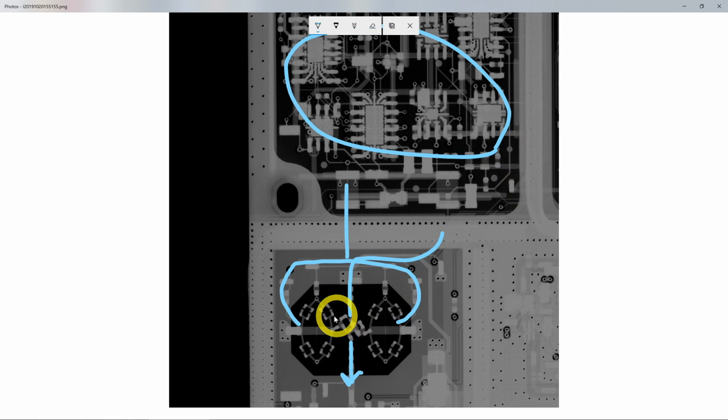So I was beginning to suspect that perhaps some of these diodes are bad, and if the diodes are leaky, they can completely change the characteristic and the tuning voltage of the VCO and the KVCO across the band of operation. So that might be one possibility. So I want to change some of these diodes, remove them, measure them, and see if there's any problem with them. I don't think there's anything wrong with the circuitry up here, because it does work, unless again the slope of some op-amp has changed and something is partially damaged but not completely damaged. It's a very difficult thing to find.